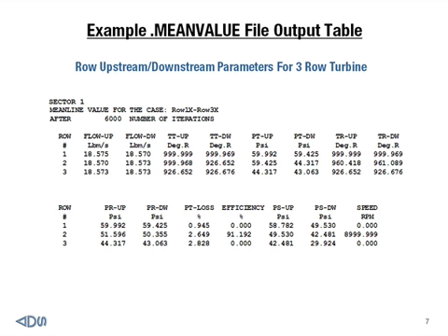and the next 2 columns here, which are now blocked, provide the upstream and downstream total flow. The next 2 columns provide the mass weighted total temperature in the absolute frame of reference. Next 2 columns, the total pressure, again flow weighted in the absolute frame. The next 2 columns, total temperature, but now in the relative frame. The next, the total pressure in the relative frame.